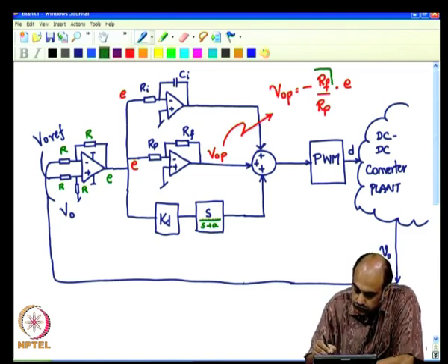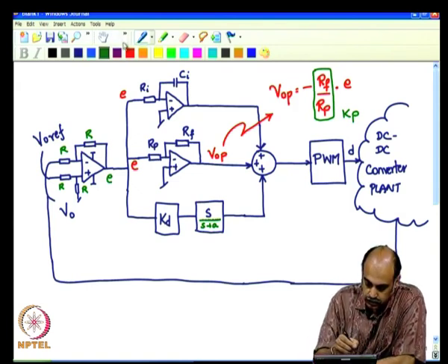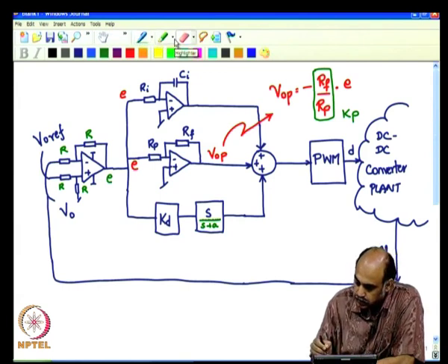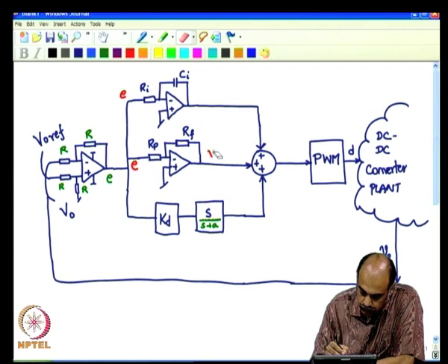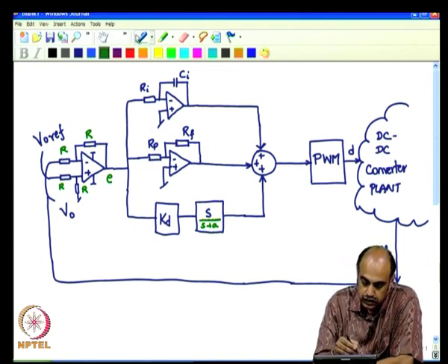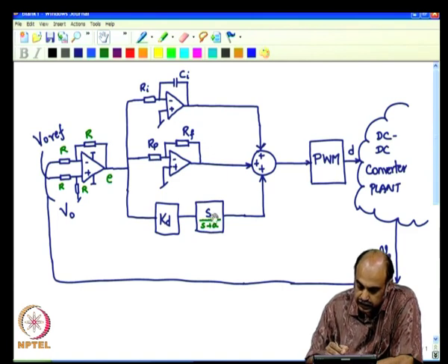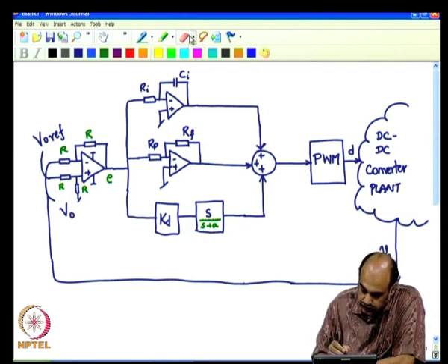This portion is the proportional gain K P that we have been using till now. So, that is the implementation of the proportional part using op amps. Notice the change of sign inversion there, we are using an inverting amplifier. And let me again erase this portion to clear up the board. And let us see what we need to do for the next component, which is the derivative component.